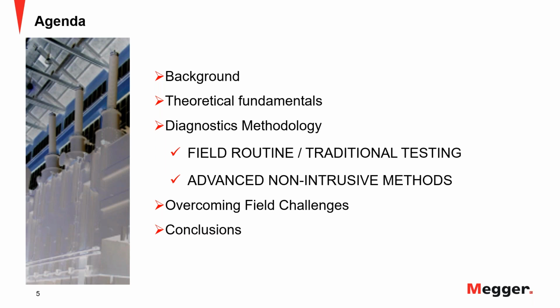We're going through some background motivation for this presentation, some theoretical fundamentals, then we're going to go in depth into the diagnostic methodologies that we have for OIP bushings, what is for the field as routine testing, and what is advanced and non-intrusive methods. And then we're going to talk a little bit about the field challenges that we can encounter doing some testing of high voltage and extra high voltage bushings, and we will draw some conclusions out of it.